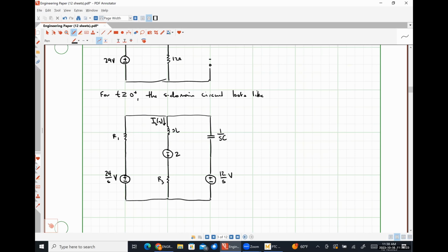Okay. So first thing, I want to make sure that we are consistent with the S domain equivalent circuits for capacitors and inductors that I've given you guys previously. So have I made any mistakes there about polarities or anything like that? I don't believe I have, but let's just make sure. Everything seems groovy. All right. So because we used nodal analysis for the last problem, let's throw mesh analysis at this one. Also, there are a pretty significant amount of nodes now that we have all of those initial condition voltage sources and all that kind of stuff thrown in here. So mesh analysis is probably also the easier system of equations to write.